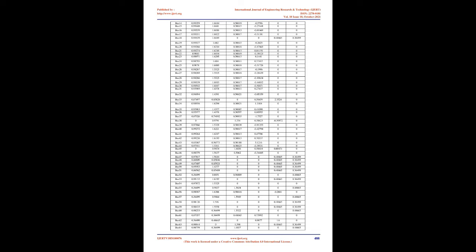The continuation power flow method uses the conventional Newton-Raphson method at the base case, where lambda equals 0, to compute the base power load data. Continuation power flow process is applied to the 86 bus network system with reserved energy resources. Jacobian of the first load flow, Newton-Raphson, is used in the predictor step to predict state variables for the next loading factor, LF. The corrected state variables can be found in the corrector step.